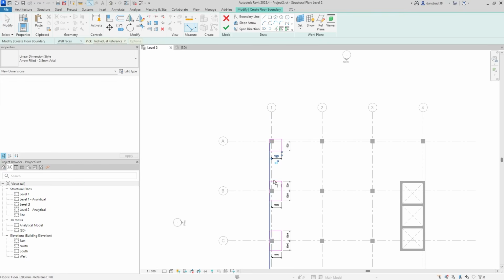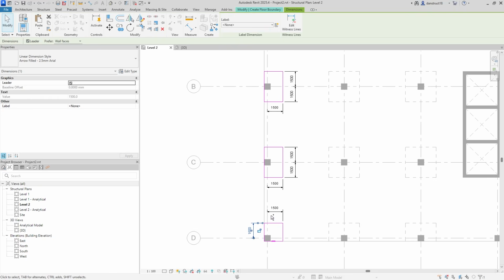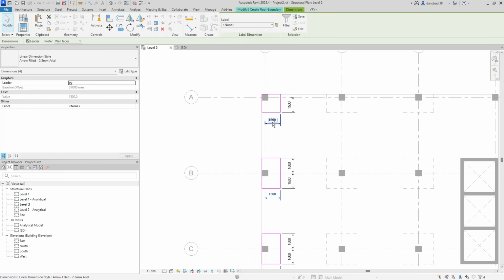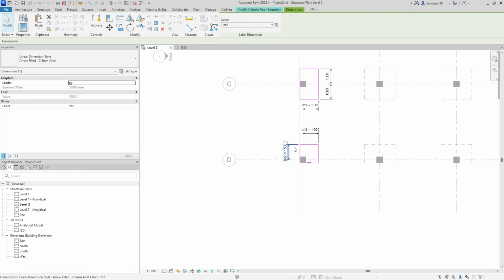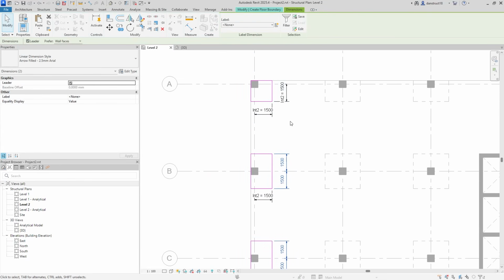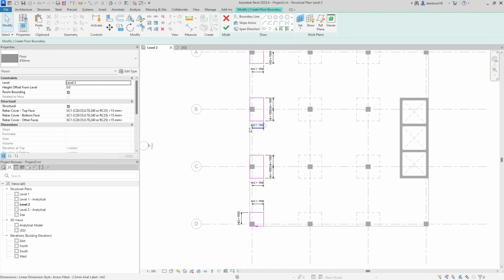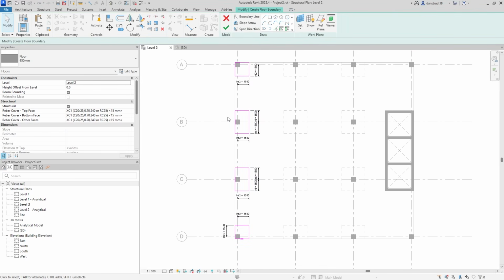So once I'm done, just click on modify. Now I'm going to select the dimensions that I want to map. So to global parameters, I'll select this, hold down control while selecting them, just like this. And I'll set this here to be int2. The same way as well, I'll select this. This also as well should be int2. And this as well, okay, this is already int2, that's fine. Now I'll select this, hold on the control key, select both, and I'll set it here to int.